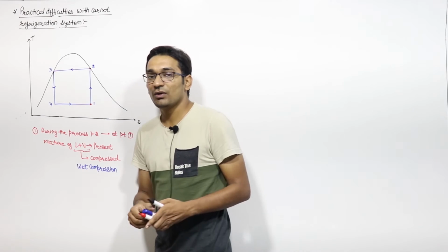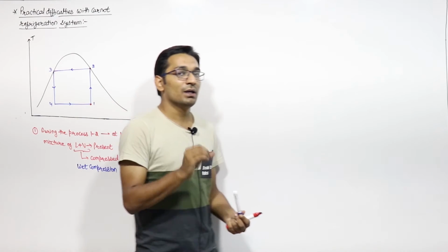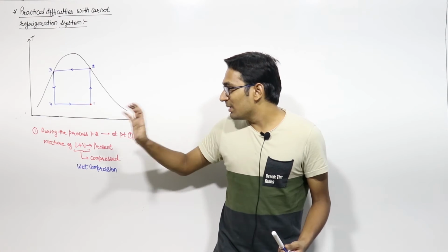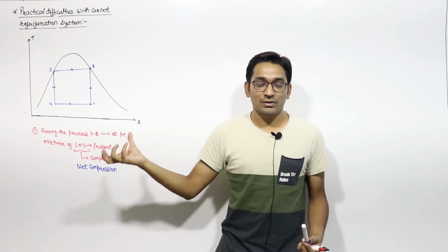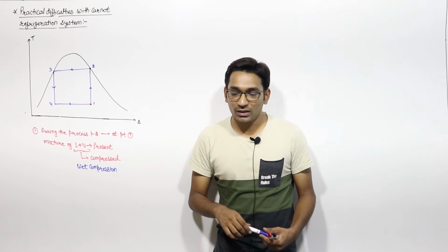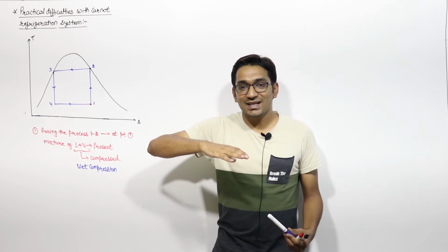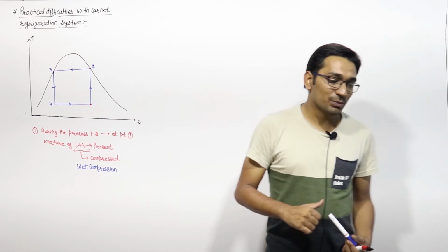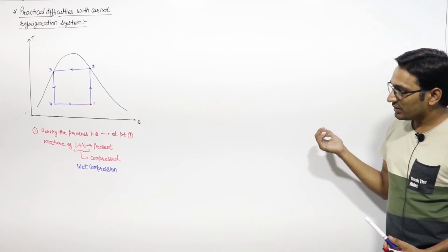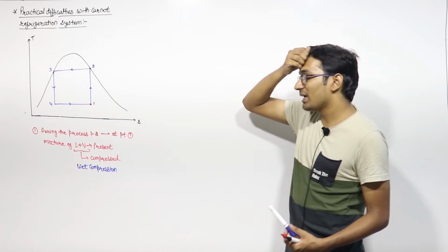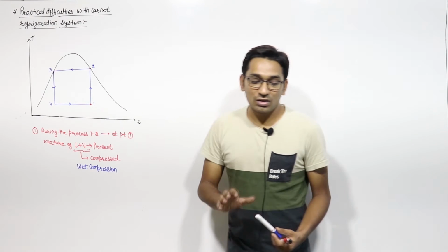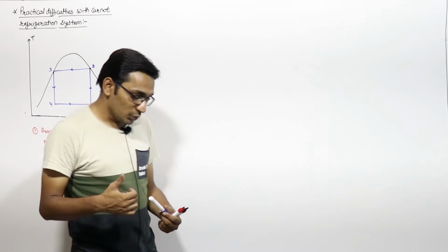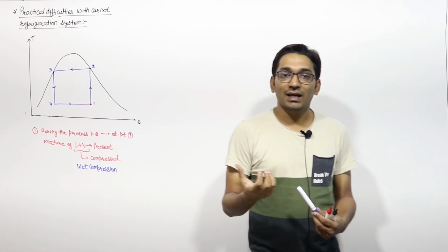We will discuss it later in fluid machines when we talk about pumps, where there is a very limited difference between a pump and a compressor. But compressing liquid plus vapor simultaneously is not practically possible, especially with a reciprocating compressor. This is the first problem: wet compression is not practically possible, especially with a reciprocating compressor, and if you want to run it at a very high speed.